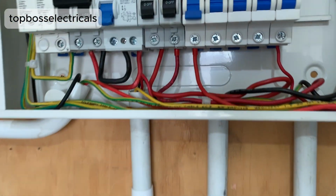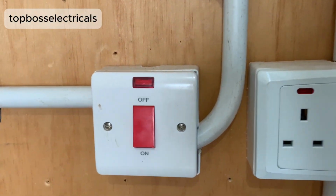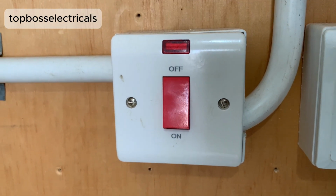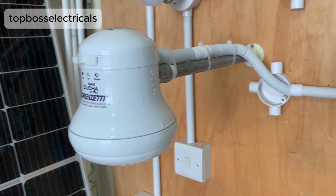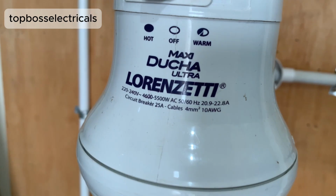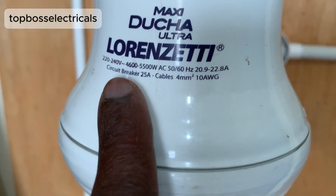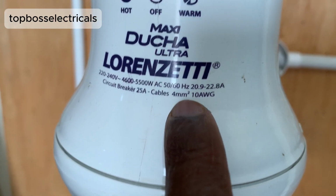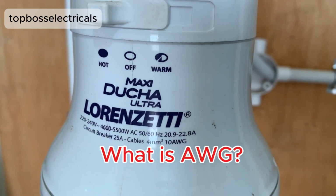When it comes to the instant shower circuit, it is important for you to also consider a 4.0 mm cable. Why? Because in many cases you'll find that this instant shower head will draw a lot of current simply because it is also a heater. When it comes to the manufacturer's directive, for this type, which is a Lorenzetti, the circuit breaker is 25 ampere and the cables are 4.0 mm squared or 10 AWG.